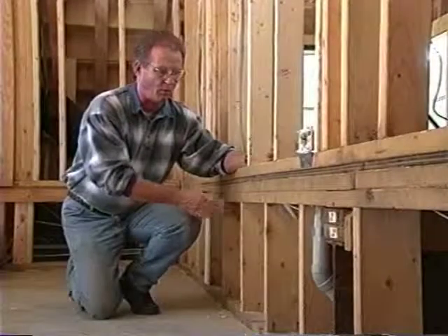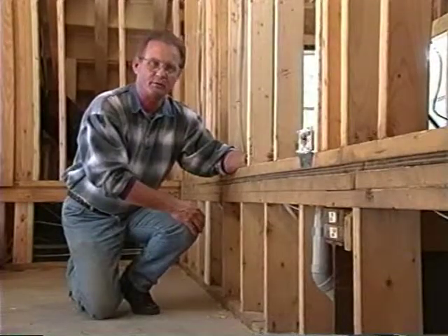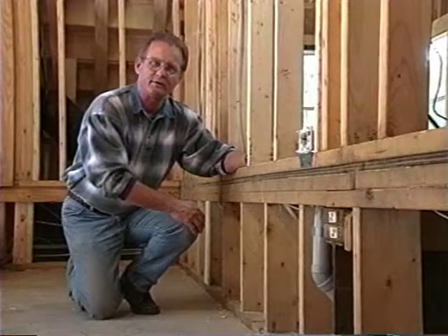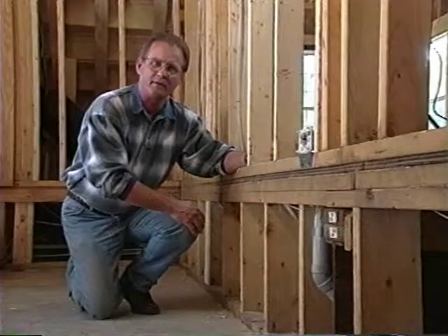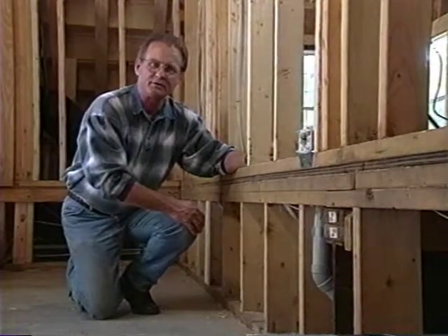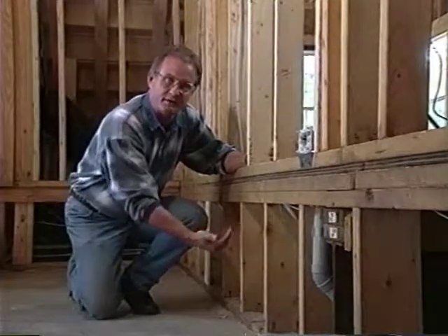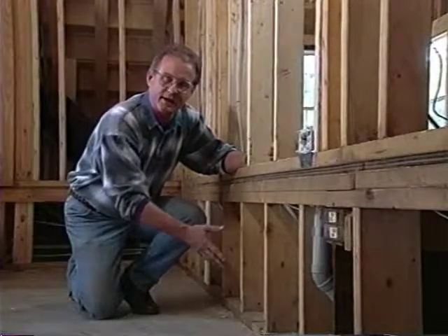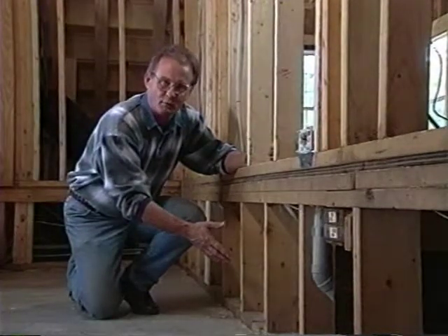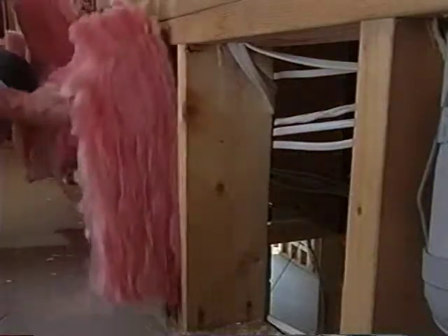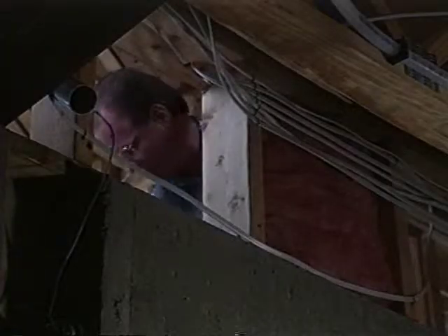No matter whether it's the wall, a ceiling, or a floor, it is critical that we determine the location of the air barrier. Often, many trades think that placing insulation between the inside and the outside creates an air barrier, but they're wrong. That's right. Insulation is not an air barrier. It slows the movement of heat, but it does not stop the flow of air. Watch what happens when smoke is blown through a piece of insulation. You can see the air moves easily through it.